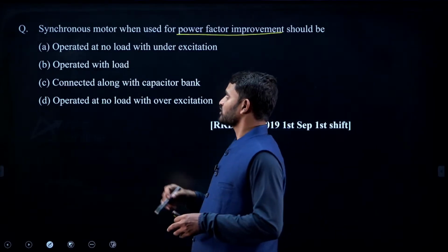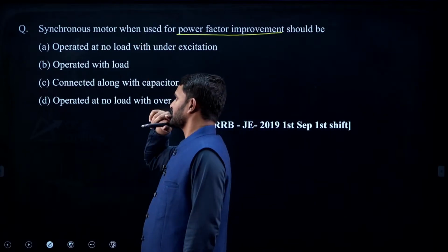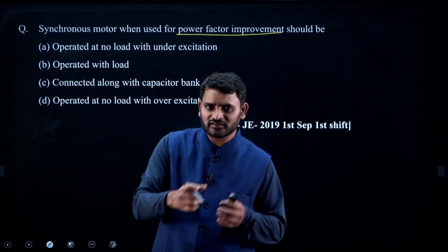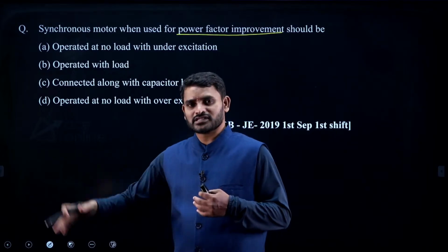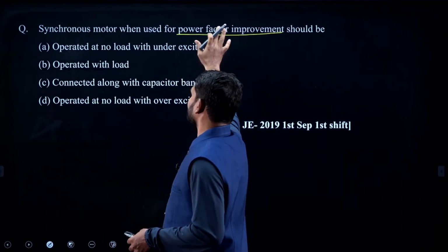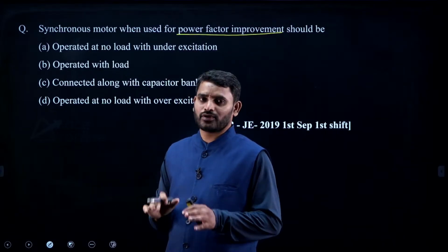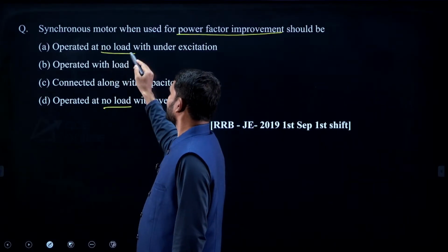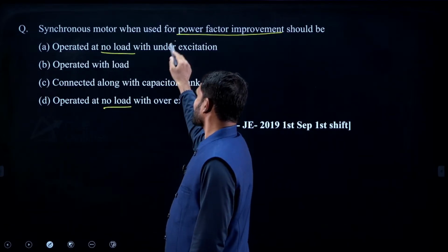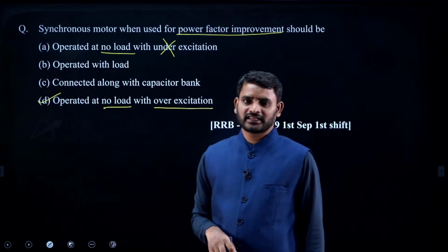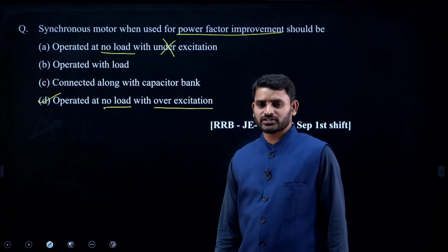So it has to be operated at overexcitation, generally no load, because if you put some load, the synchronous motor will draw some active power and that will be supplied to the mechanical load. So if you are using it for power factor improvement, no need of putting a load on it. Generally it is operated under no load, and it should be over excitation, not under excitation.